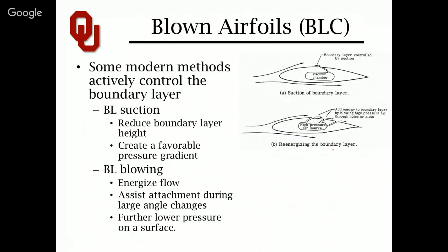We've discussed this a couple times just in passing, the names of blown airfoils, boundary layer control. That's what BLC stands for. This is a research area that has had a lot of money put into it. There's some very interesting aerodynamic things happening here, but overall the biggest penalty of this is the hardware, the mechanisms, the added complexity and added possible failure points involved with establishing these blowing and suction systems.